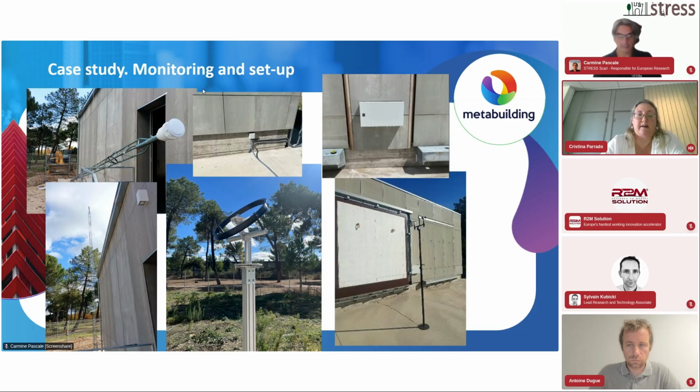As Antoine said about the sensors, we have fixed sensors on the outside: a weather station installed at 10 meters on the north wall in a pivoting tower. We have pyranometers to measure the direct and the diffuse radiation. We also have sensors positioned in front of the test wall. Everything is connected by this external electrical panel, so we introduce the cable to the cell. And next one.